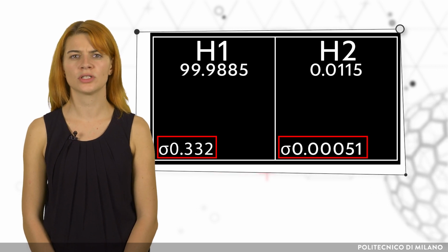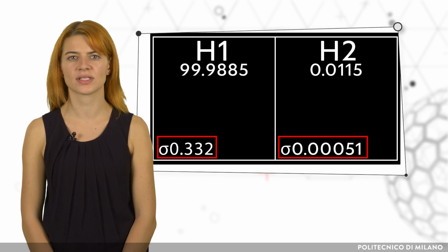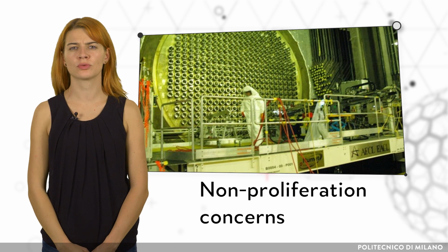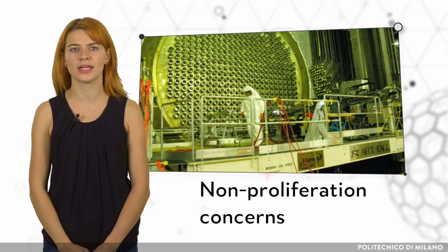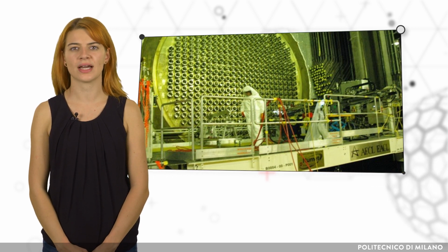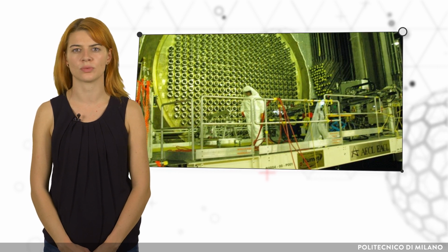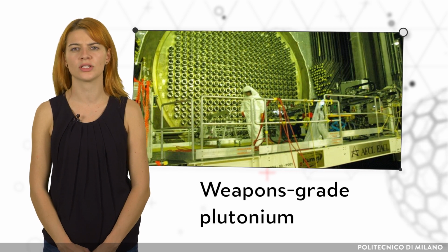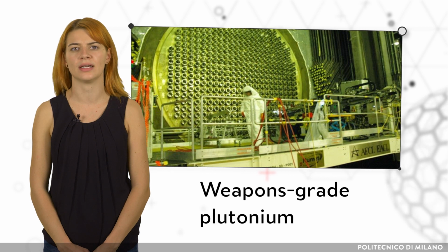As a result, fewer neutrons are absorbed by the moderator, and therefore heavy water reactors can be operated with natural uranium. In the context of non-proliferation, pressurized tube reactors like CANDU and RBMK reactors have to be considered critically, since these reactors are designed in order to allow the replacement of fuel elements during power generation. Thus, it is possible to replace the fuel after a short irradiation time and thereby obtain weapon-grade plutonium-239.